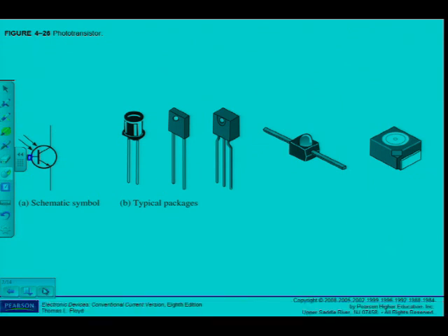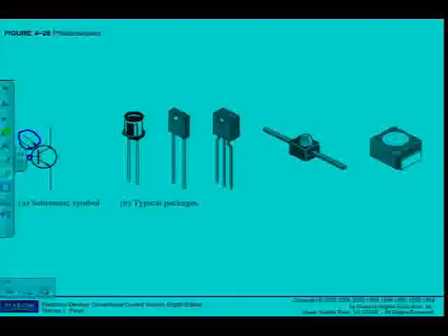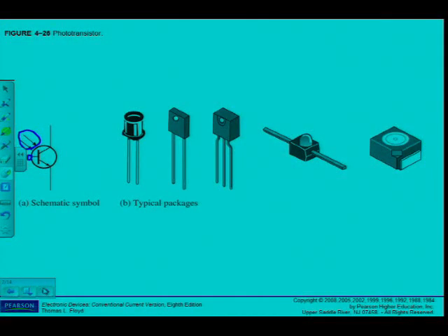It's sometimes a 3-terminal device, so I can operate it as a normal BJT. But most of the devices only have 2 terminals, and as we've read, it's light activated. You can also see that these 2 arrows pointing towards the transistor symbol indicate that this is a phototransistor. Alright, so make sure that you know the schematic symbol of a phototransistor as well.